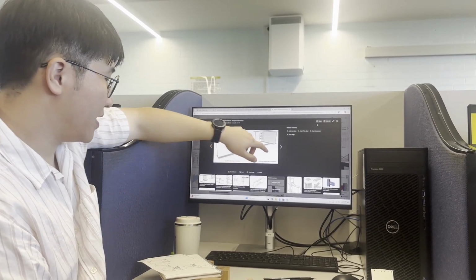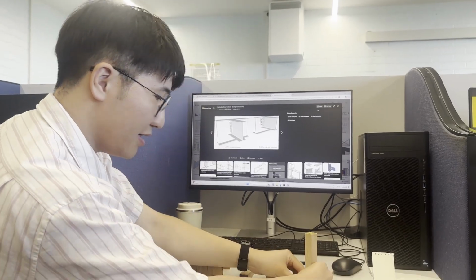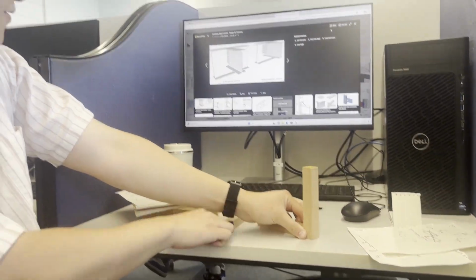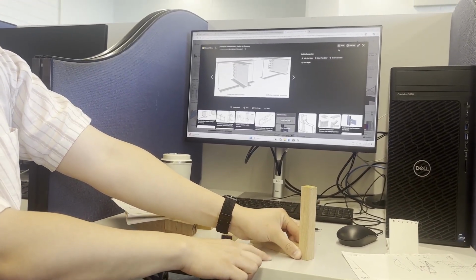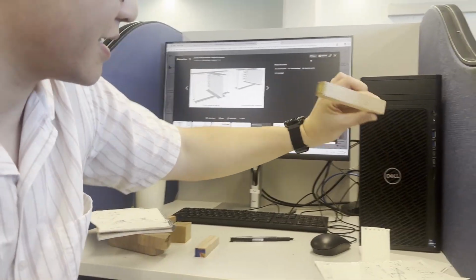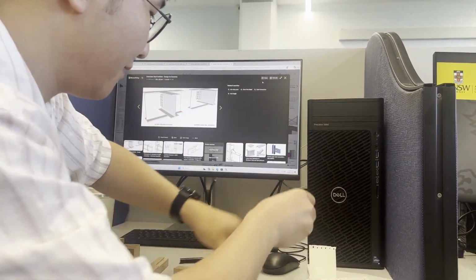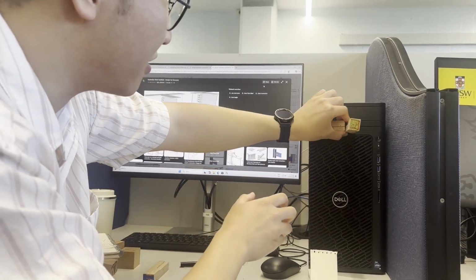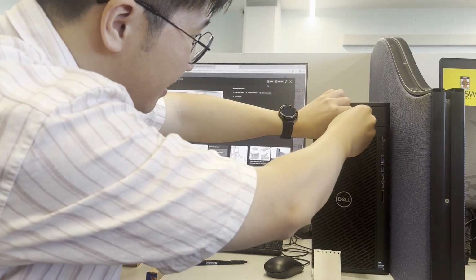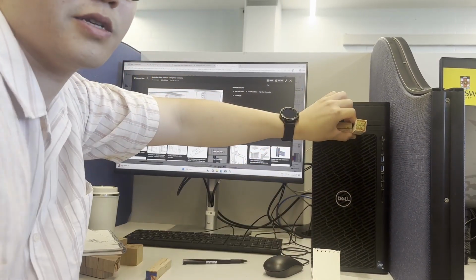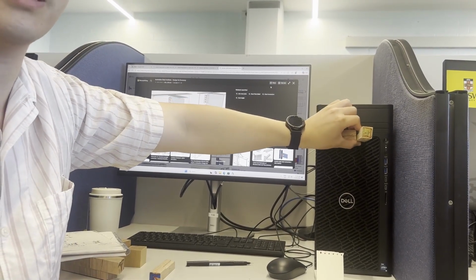This is better because an equal angle is already at 90 degrees. So it's harder to mess up the weld on site, do you know what I mean? If this already comes like this, instead of perfectly needing to align this and then weld it, this comes at a 90 degree angle. Oh great, we already know that this cleat is going to be at 90 degrees. Now we can weld on site more easily when it's against a flat surface.